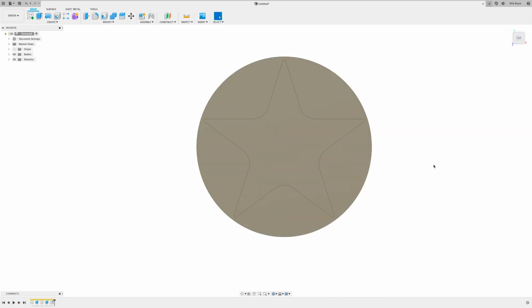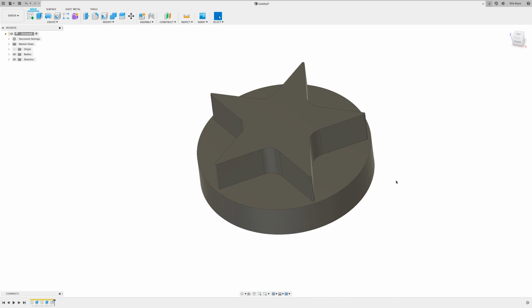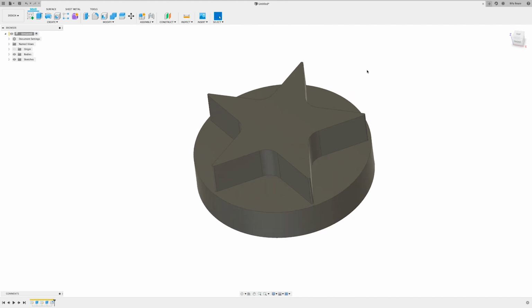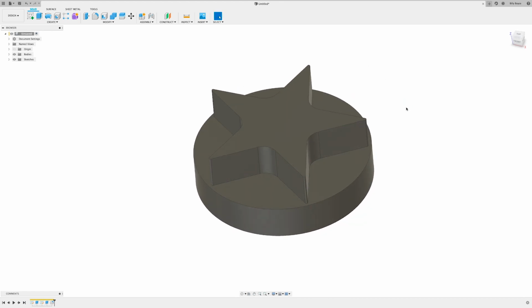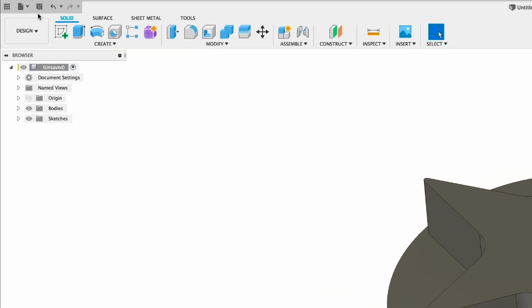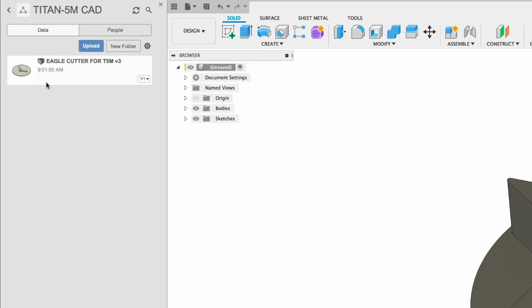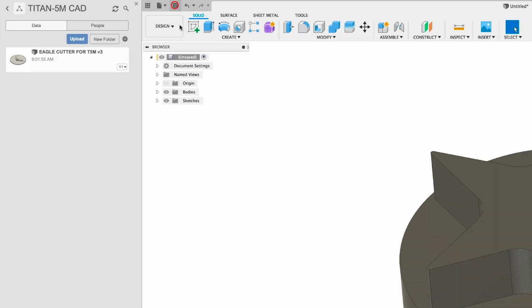We're going to use that to kind of mimic what the engraved looks like, and then that'll also give us a tool path line down the center of the engraved, which you'll use when you go to the cam portion. So the way we're going to do that is we can click this guy right here, and that'll open up where you stored it in Fusion, the cutter. And now we need to save before we can bring anything into it. So go ahead and hit save.